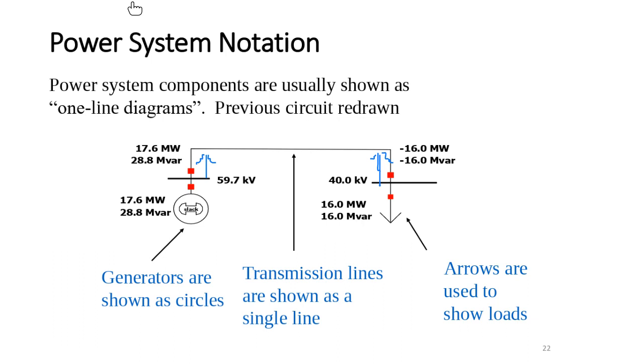Therefore, if we have a capacitive reactance, for example a capacitor, this is part of the load. Then what happens here? This also will give reactive power up to this bus. Either it will be absorbed by the load if it's enough. That's what they do in the industry. They install capacitors for this reactive power, because we don't want too much reactive power from the transmission line.